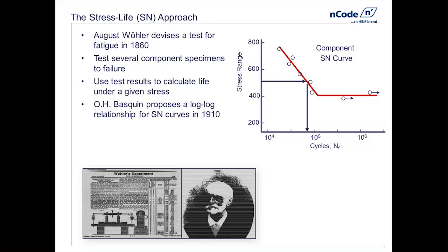And he found out that if he put in a constant load, which meant a cyclically varying stress as the axle rotated, after some time the axle would fail. No surprise. Each one of these dots here was a failed axle, and he found out that if he ran at different loads, or hence stresses, axles would fail at different times. You can plot it up on a curve like this, and you can see from this that the higher the stress going this way, the shorter the fatigue life, which these days we take for granted. The higher the stress, the bigger the stress cycle, the shorter the time to failure.